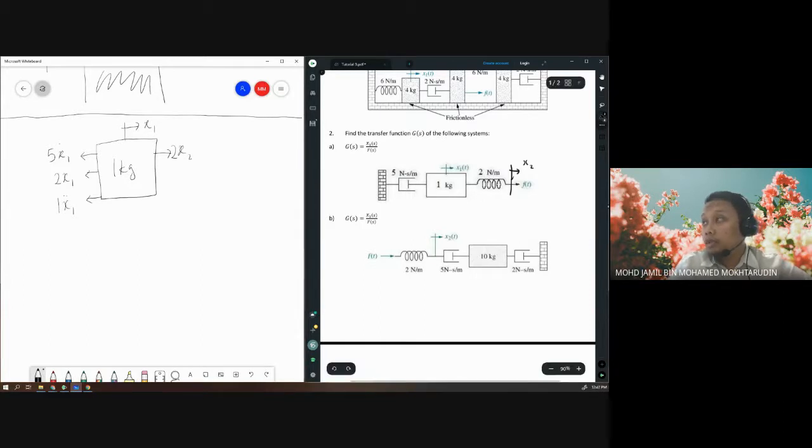And now consider the second free body diagram, x2. So x2 is just a point without any mass, so we don't have a mass here. And on x2 we have a spring connected to x2, so we have one backward force trying to resist the motion of x2. And then the spring is also connected with the box, so we have a forward force to x1. And then we have the input force F on x2. So we apply F, and no inertia because there is no mass on x2. Okay? So now you have the free body diagram. You can write the equation of motion and solve as usual.